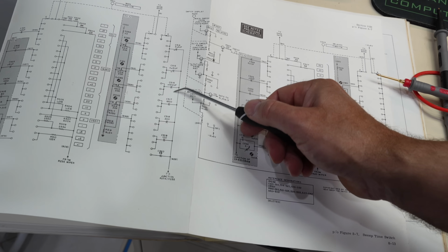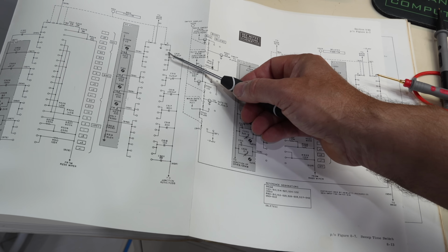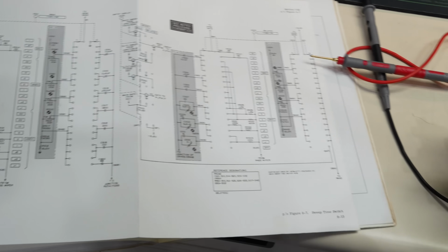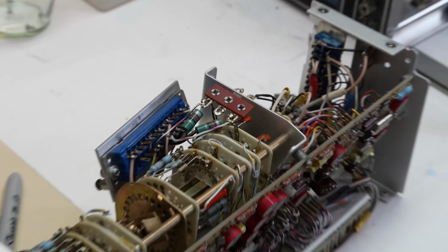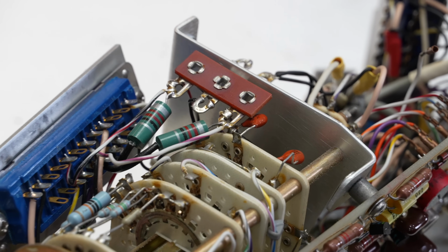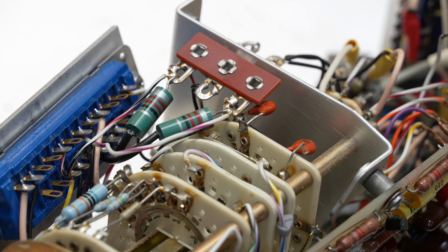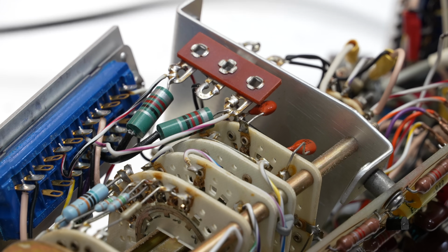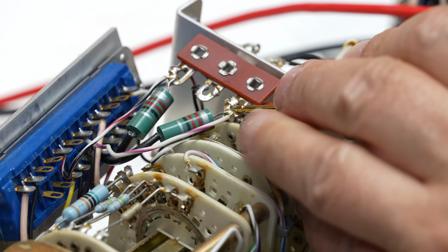So depending on the speed, the hold-off time is changed. And there is no minus 12.6 volts in there at all. Then finally I looked at this guy over here, and this is minus 12.6 volts. So my theory is that this is touching something it shouldn't.